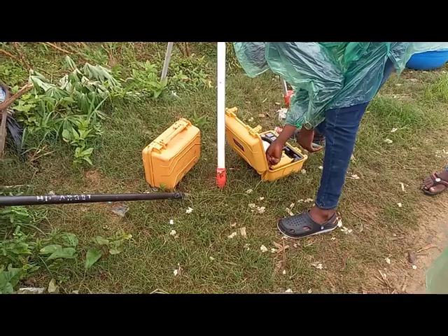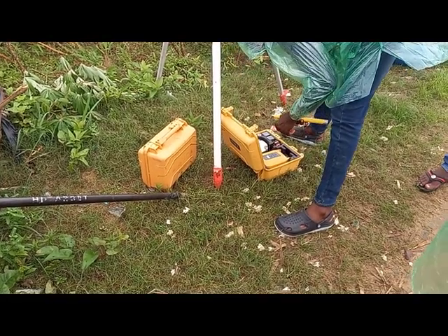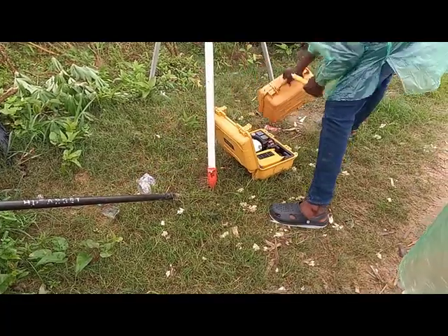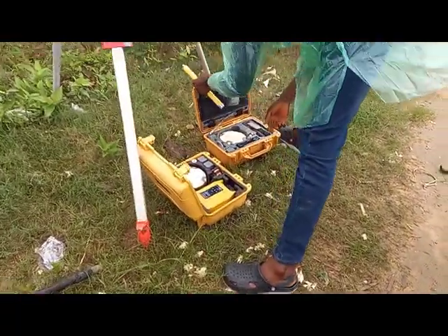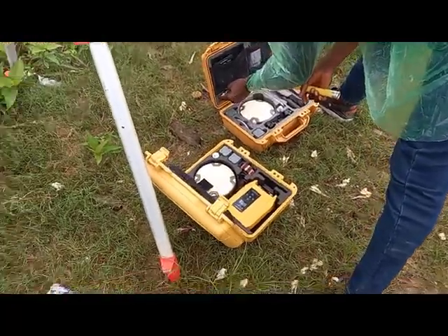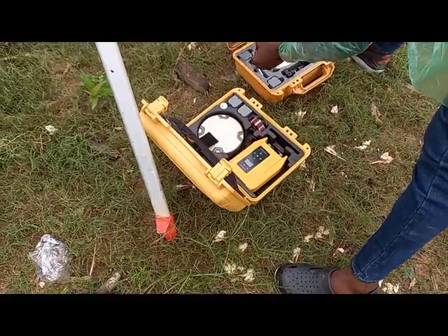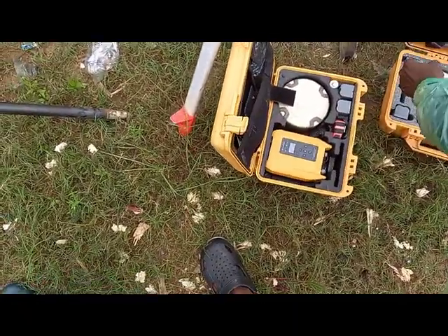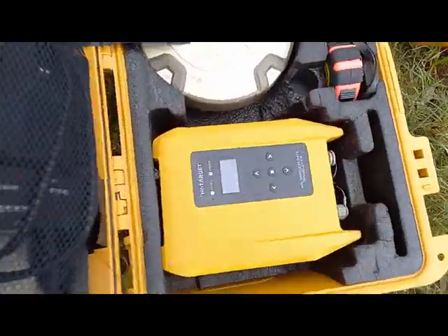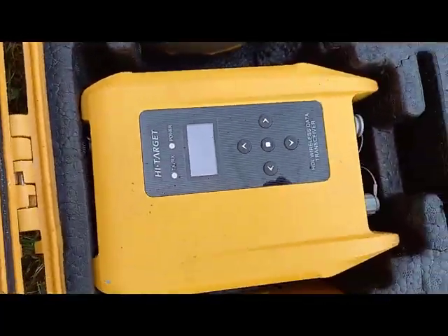It's updating it for you automatically. That's basically what RTK means, real-time kinematics. So it's a more advanced feature. Rather than going later to apply correction factors and do manual calculations, RTK does the automation of those corrections of satellite position and the actual location on the ground.